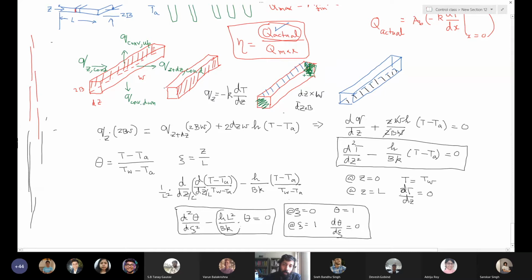So this is our dimensionless group. Because everything in this equation is dimensionless, this has to be dimensionless. You can check it, but you will find it to be dimensionless. Every dimensionless group is a ratio of two properties. Dimensionless groups always weigh two things. So which two things is this weighing? Convective to conductive. Convective to conductive what? Heat transfer. Convective heat transfer to conductive heat transfer.